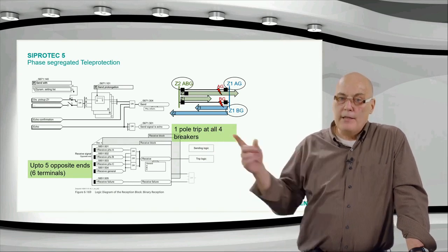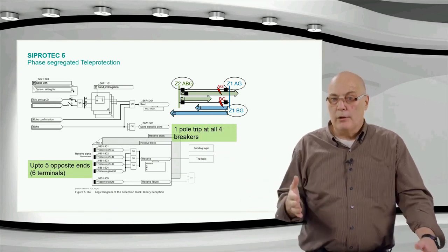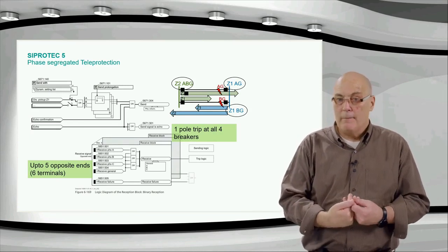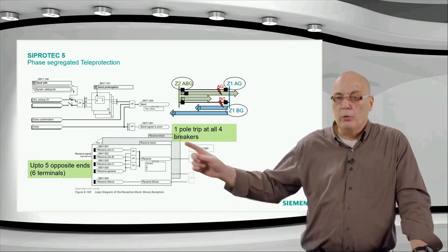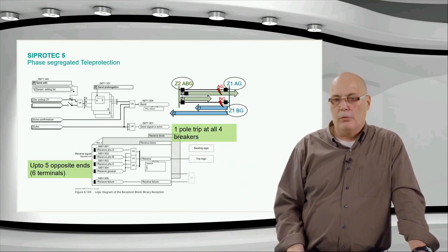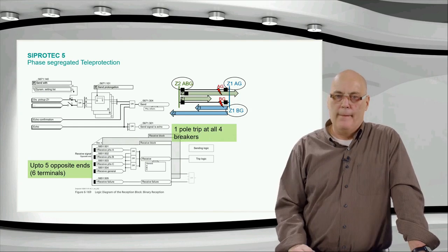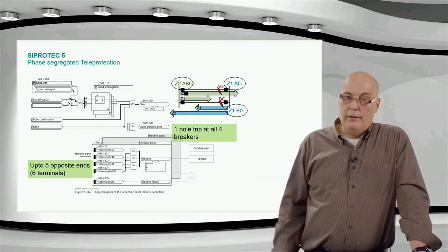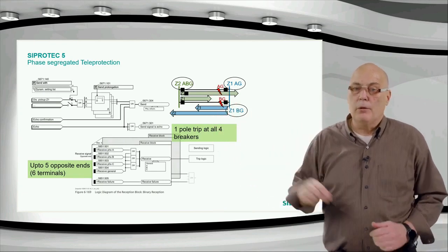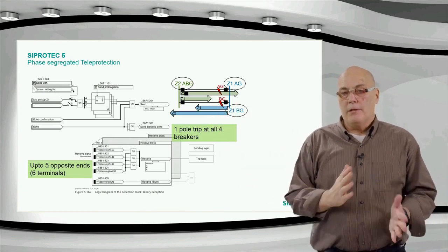And in these applications, double circuit lines, your dependency on the teleprotection is higher, right, to get secure tripping, because you would probably have to set your zone 1 smaller to make allowance for the influence of parallel line coupling. So the teleprotection is extremely important here. And the other thing that can happen on these double circuit or multi-circuit lines, you get inter-system faults.